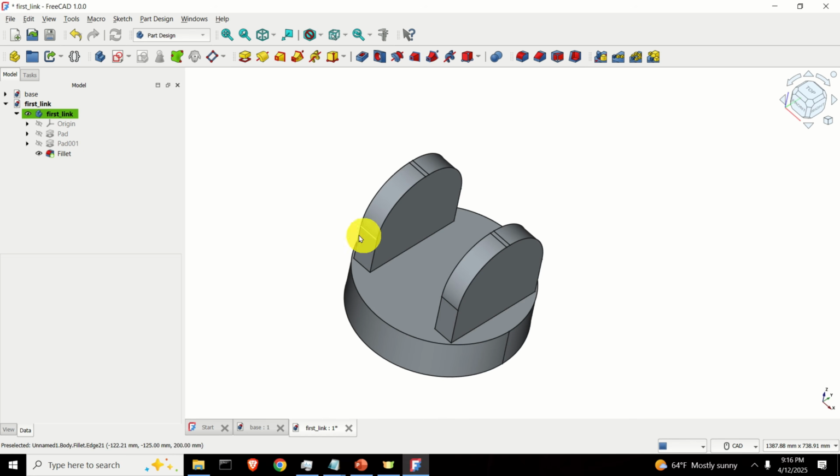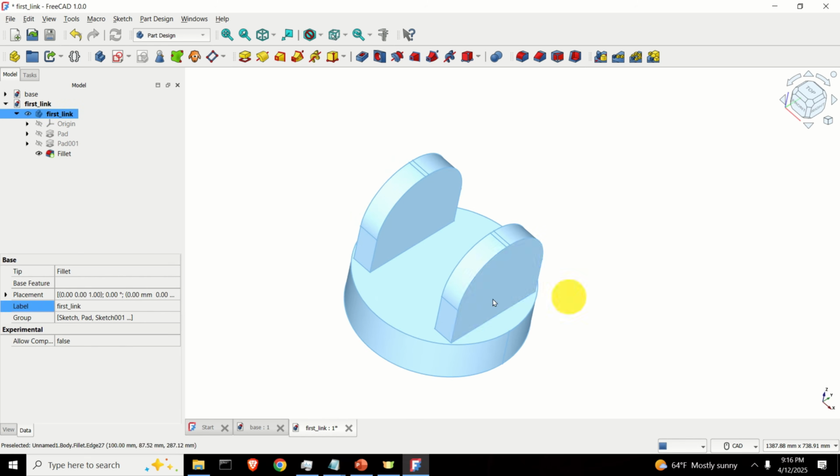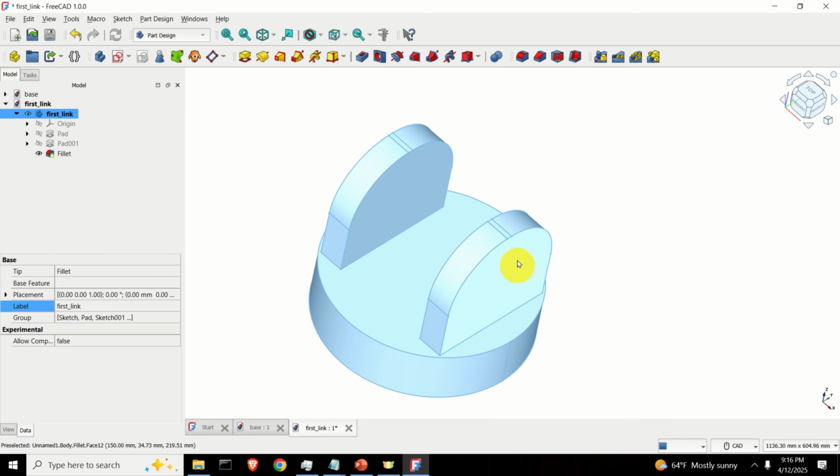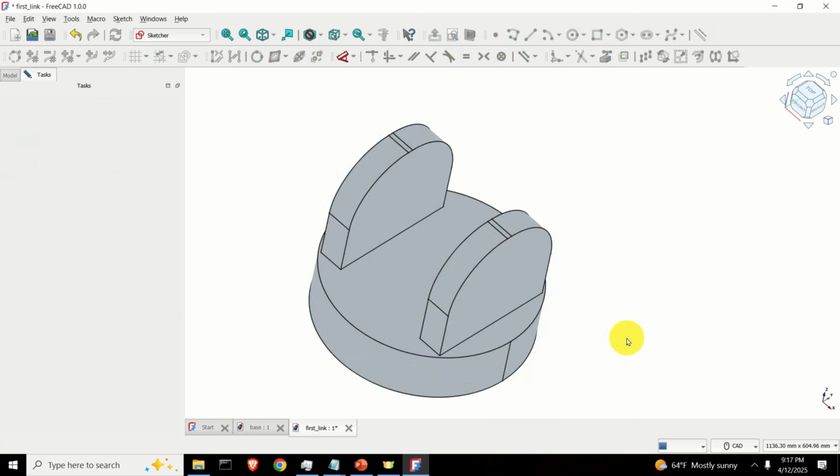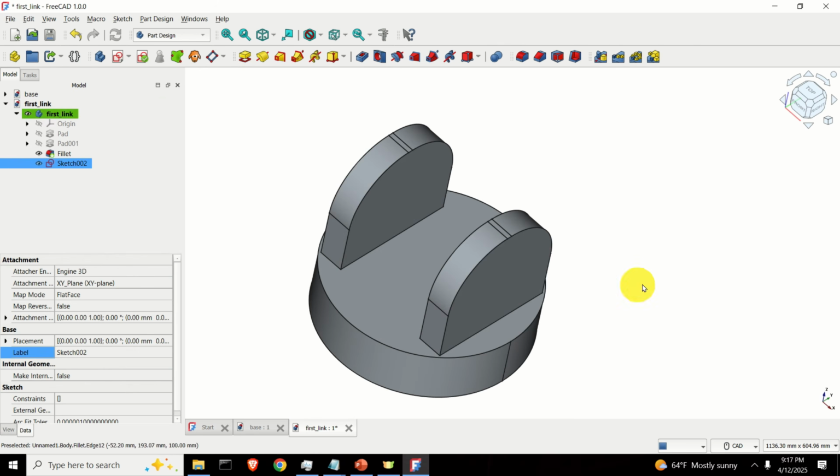how to do that. To do that, click here. And what we need to do is to create a hole over here as well as over here. Or better to say, not holes, I need to correct myself. We need to actually create a cylinder and then extrude it from here to here such that we can have a nice rod. To do that, click here and then click here and select any plane for the sketch, close, and let's map the sketch to this side.